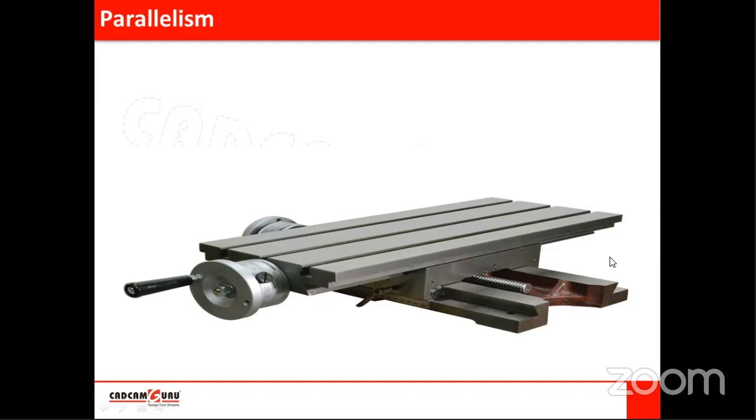For angular guideways we cannot apply parallelism, but if the guide surfaces are parallel to each other, vertical or horizontal, any can be the orientation of the surfaces, but both should be parallel to each other. In that case, we can apply parallelism. Or a simple example you can take is a drawer of your table. The table can be wooden or metal, but you can think of a drawer of a wooden table.